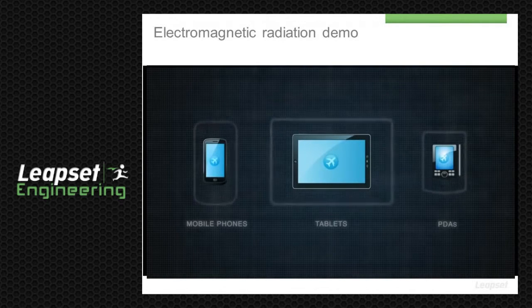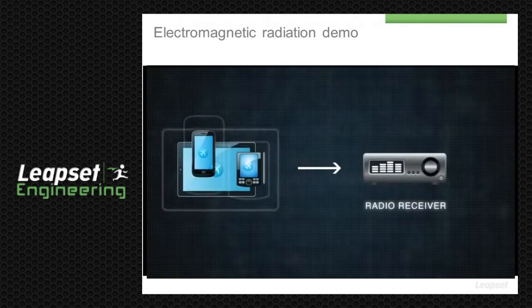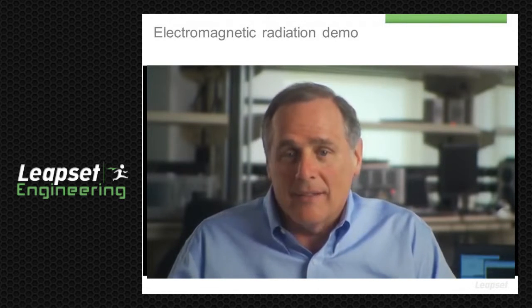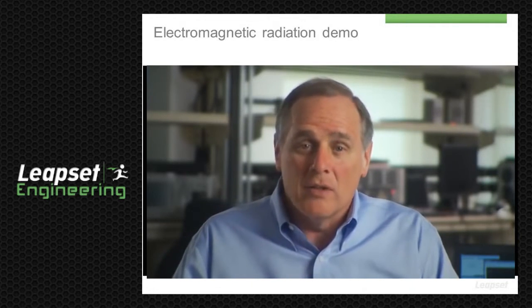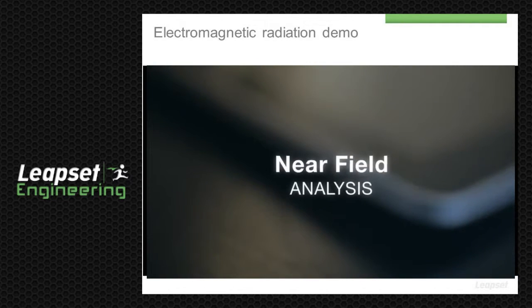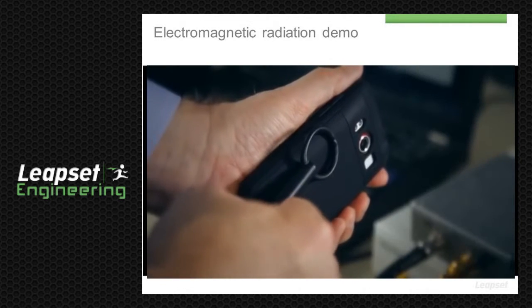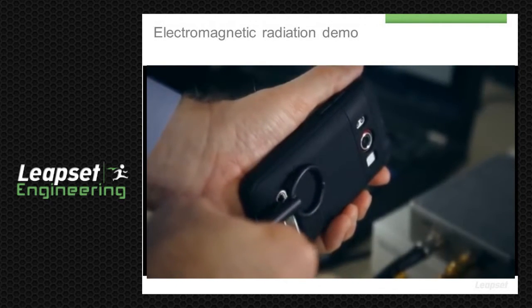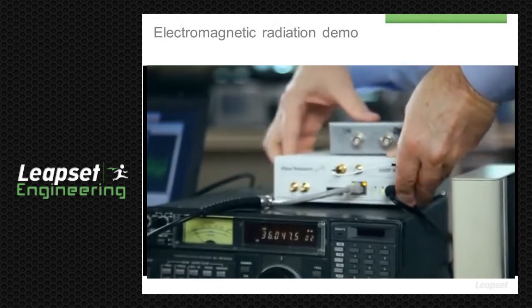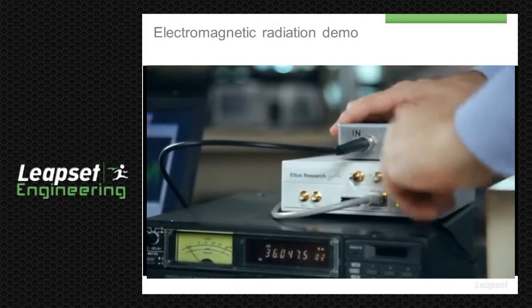This unintentional electromagnetic radiation can be picked up using a common radio receiver. By digitizing and analyzing these signals, we can extract and decode the secret keys used in the cryptographic algorithms. Leakage signals can be picked up by a probe that's as simple as a loop of wire that responds to the magnetic field coming from the device. This wire loop is connected to the radio's antenna input. The radio intermediate frequency output is connected through a home-built amplifier to an inexpensive digitizer.